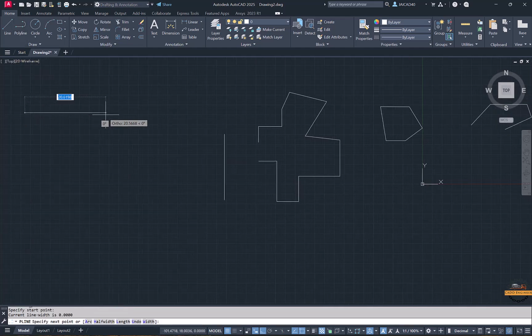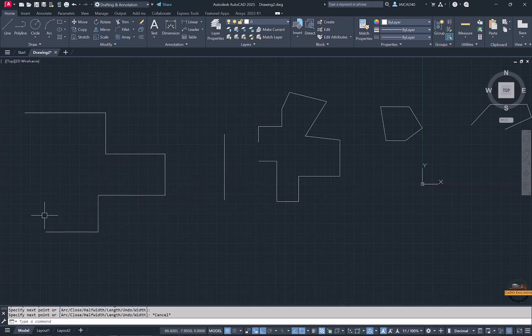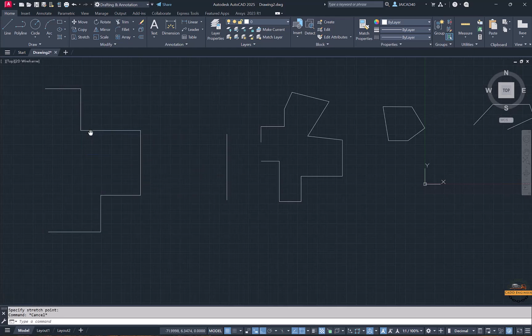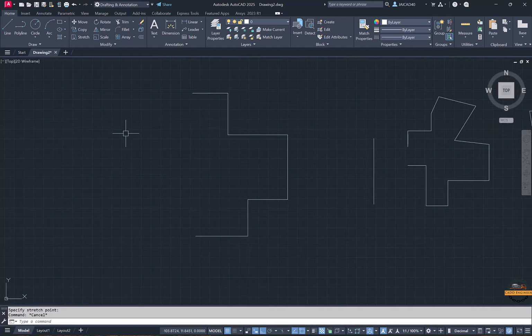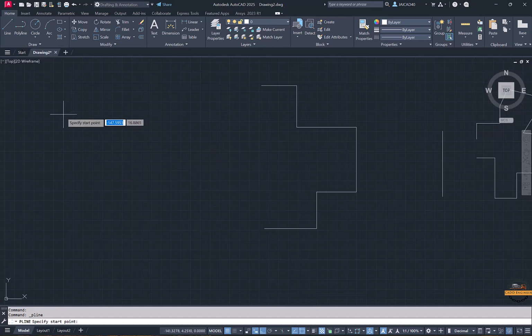If you want to make a polyline, you can just draw like this, and if we cancel that command and select this, we find that it is a single line. It means when you want to modify anything, you can see how it is modifying. It does not get separated into lines when we move the grips. So whenever you feel that you have to make a continuous polyline object, we can use this polyline tool. Not only this, we have more things here.